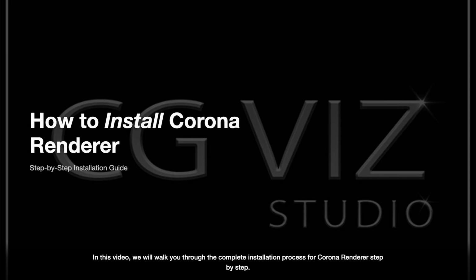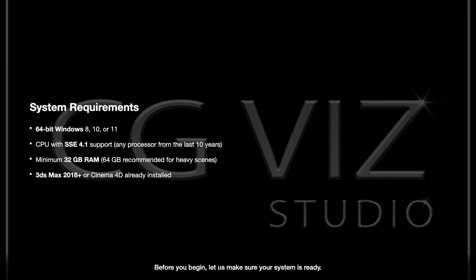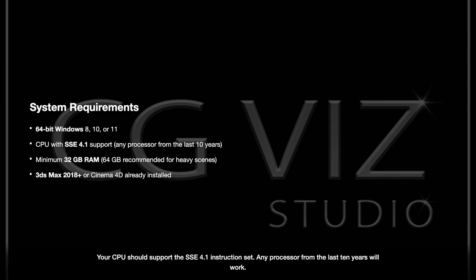In this video, we will walk you through the complete installation process for Corona Renderer step by step. Before you begin, let us make sure your system is ready. You need a 64-bit Windows operating system, either Windows 8, 10, or 11. Your CPU should support the SSE 4.1 instruction set. Any processor from the last 10 years will work.